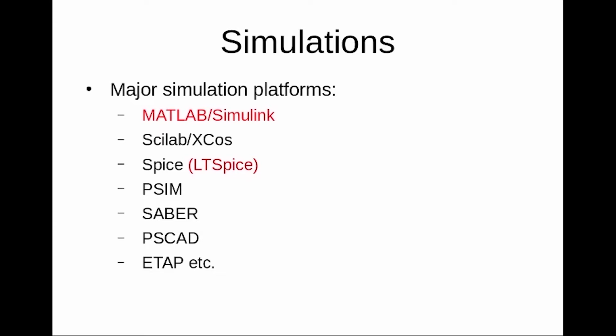After MATLAB, another popular tool is SPICE. This is a circuit simulation tool which is based on component SPICE models. In order to build a circuit model, we need to have models of each of the components. It is also possible to write SPICE models based on the components' input-output relationships and physics-based equations. Most of the component manufacturers also supply SPICE models of their components.